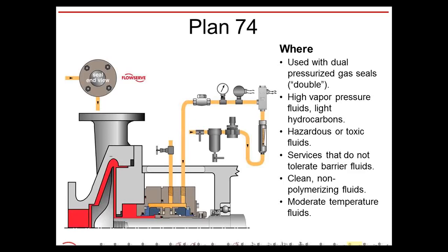Again, gas seals are always dual. They work great for light hydrocarbons, fluids that have problems with vapor margin, and very unstable fluids that you may be pumping, maybe in a vacuum pump type of situation where you have mixed phase, where it may be gas and sometimes liquid and gas. It's very wet gas.